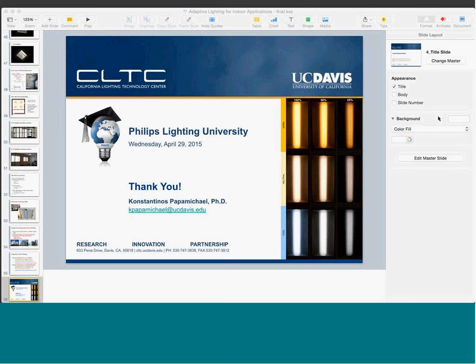In fact, quite a lot of the new ground that we cut with algorithms came when we threw the work plane illuminance out of the equation, and just assumed that the electric lighting system is enough to do the job. So algorithms are based on the signal of the photosensor based on the electric light output alone. And you have to do it at night. Just turning your lights on and off or taking them through their dimming range can give you the setting point that you want.